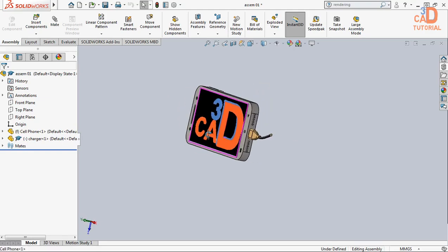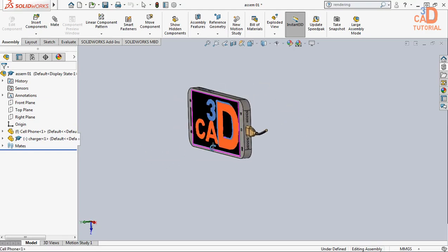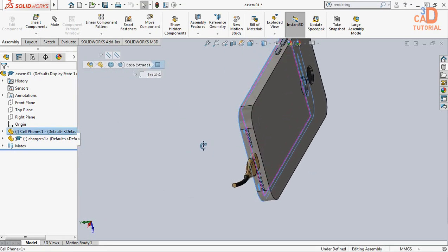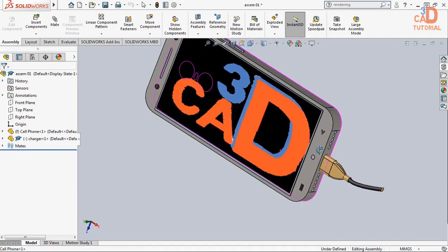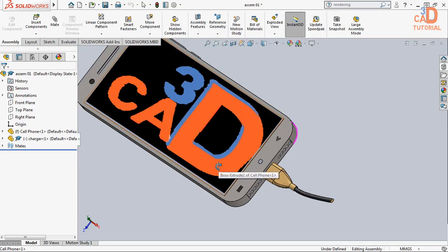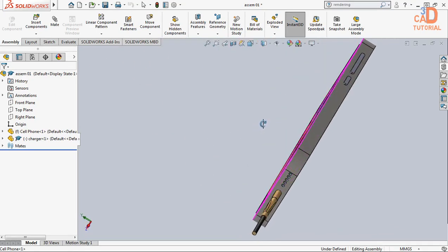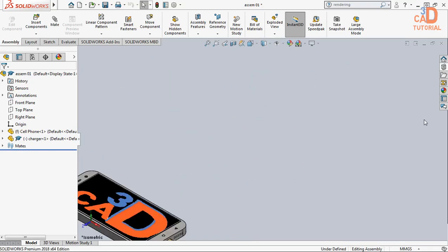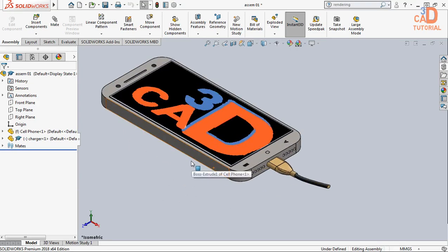In general, we will take an average of cell phones and design a stand. The existing model has a thickness of 8 millimeters, and we are considering another 2 to 3 mm as a buffer. Why? Usually people use mobile covers, which have a thickness of 1.5 millimeters. And if the cell phone is very thick, the stand should still be useful. So we have to consider all the parameters while designing even a simple product.